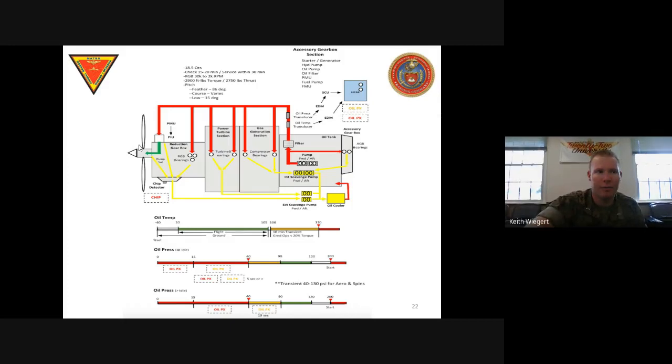We've got low pitch blades for low speeds and low throttle settings, but it is the maximum oil condition, so it's kind of counterintuitive. And then anywhere in between low pitch and feather, that's going to be our high pitch blades or our coarse blades for you.